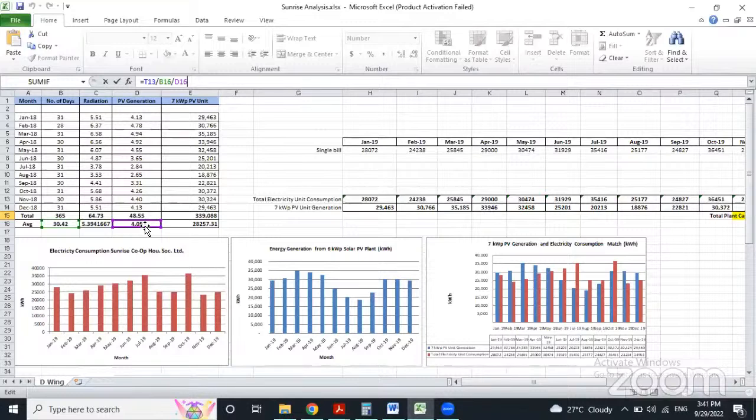This data you can get from Meteonorm software or from the NASA website. For any latitude and longitude, you can get this value. That is your PSH, the average over the day. So 4.05 for Madhya Pradesh is good enough, for Maharashtra it is good enough, and for Rajasthan and Gujarat it might go up to 4.5.